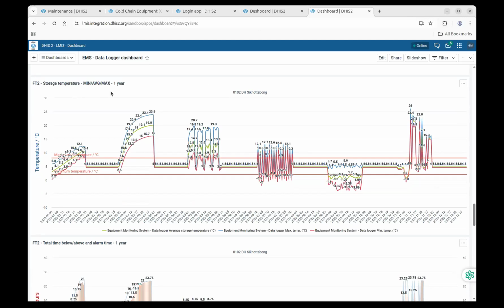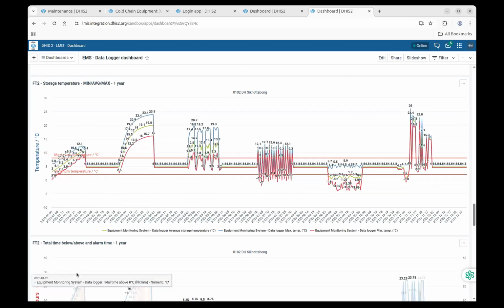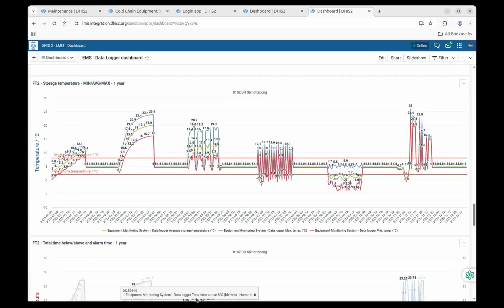We have configured some fictitious scenarios. So you can see, for example, on the first chart, you have a slow increase of the temperature. Typically the reason for that could be that there's a leakage of the coolant, or that the ventilator opening is being clogged, and therefore the cooling is deteriorating, and this would give this kind of picture.